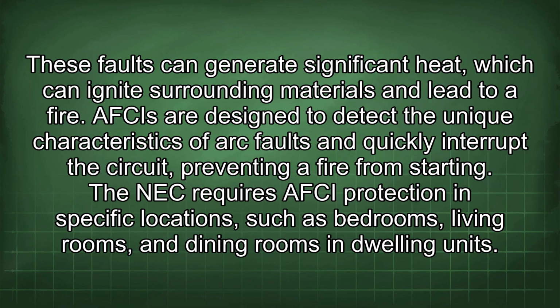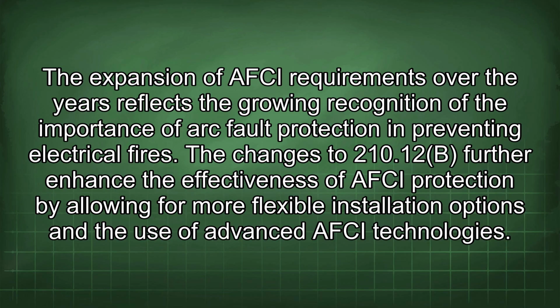AFCIs are designed to detect the unique characteristics of arc faults and quickly interrupt the circuit, preventing a fire from starting. The NEC requires AFCI protection in specific locations, such as bedrooms, living rooms, and dining rooms in dwelling units. The expansion of AFCI requirements over the years reflects the growing recognition of the importance of arc fault protection in preventing electrical fires. The changes to 210.12b further enhance the effectiveness of AFCI protection by allowing for more flexible installation options and the use of advanced AFCI technologies.